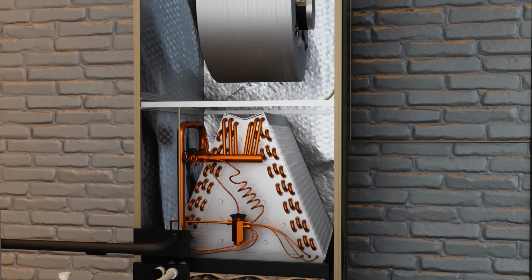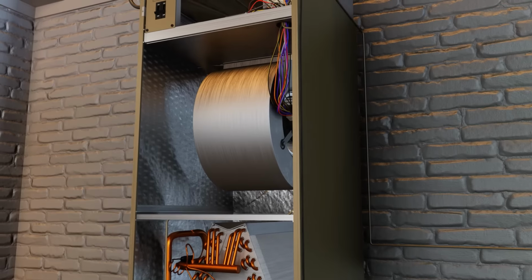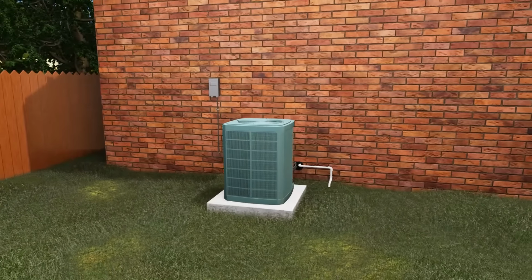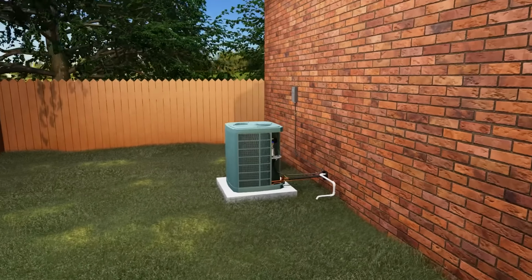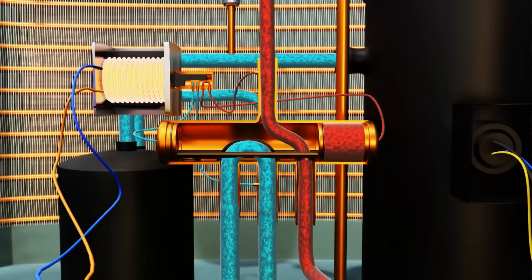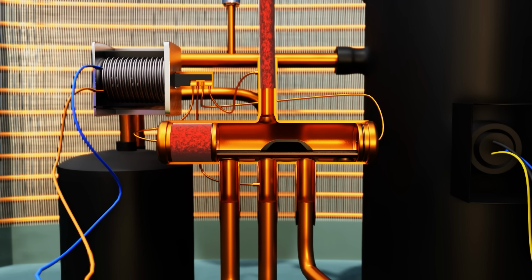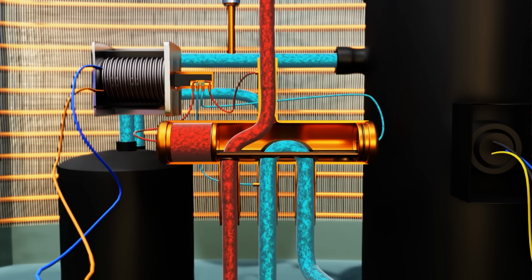This is what we call an air handler or a fan coil. The outside unit is what we would call the condenser or condensing unit, and it's also often what people will call the heat pump portion. But really, what makes it a heat pump is just whether or not it has the controls that allow it to shift from heating to cooling, to bring heat in from the outside and pump it inside. It really has a lot of the same components that an air conditioner has.